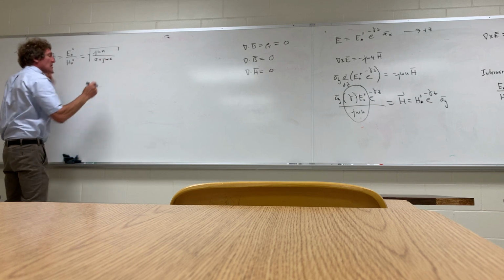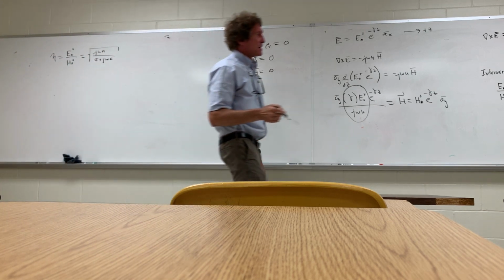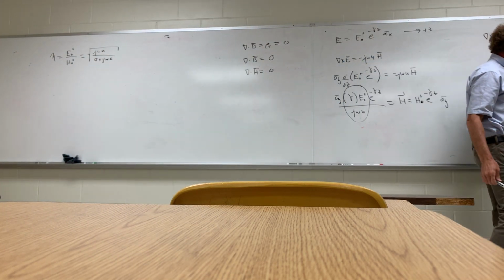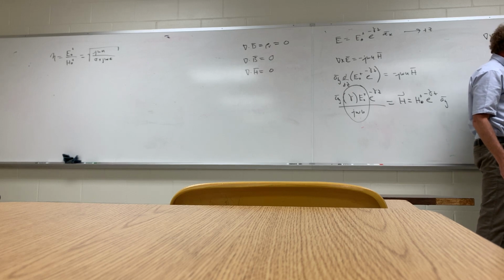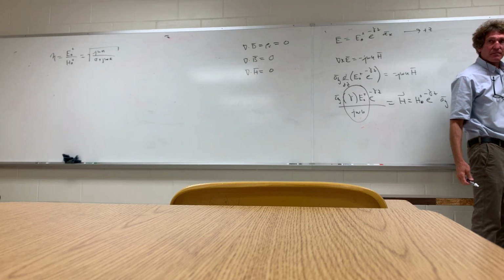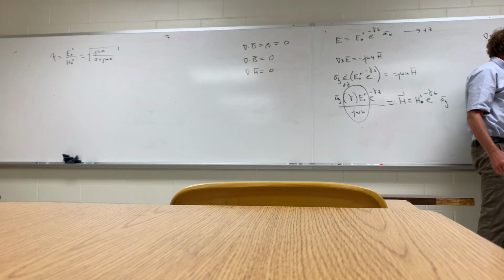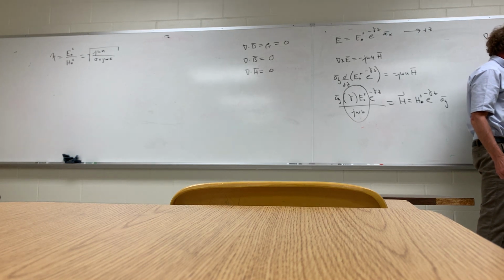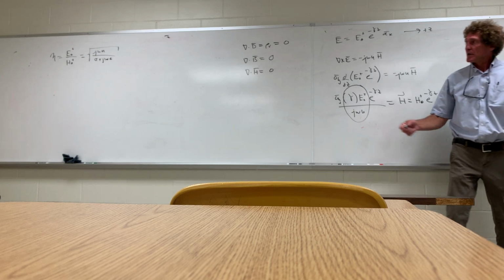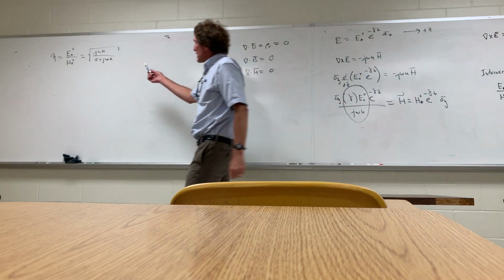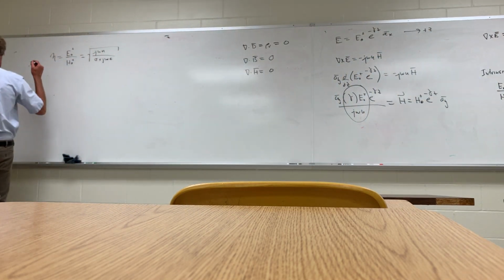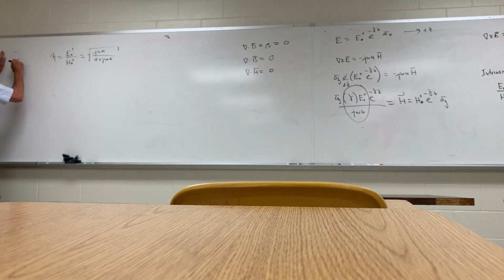Now, I want to just mention something. Here, if you look at this, you see how this is J omega, this is J omega to the 1/2 power? Can y'all follow me on that? Well, if you go ahead and square that, then you can put the square root operator there, and then you'll see J omega mu will appear there, and this J omega mu will go away, and you'll be left with this. And this is the intrinsic impedance in the region.